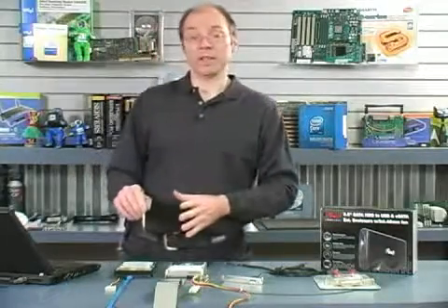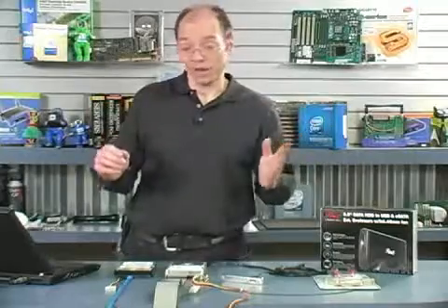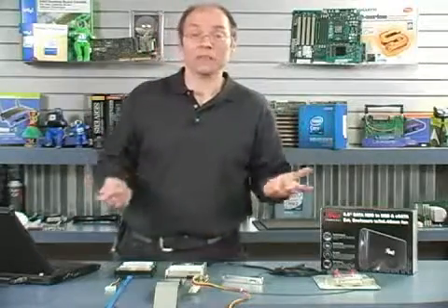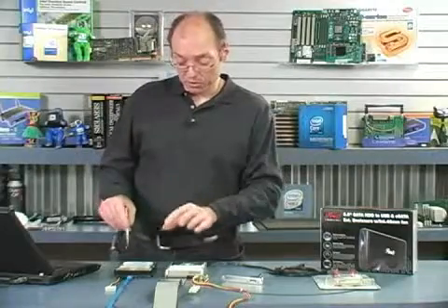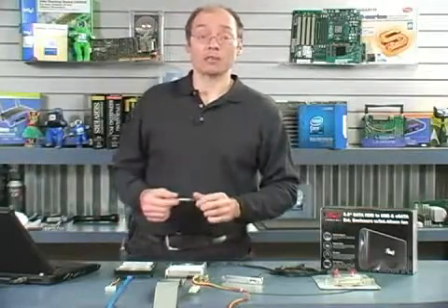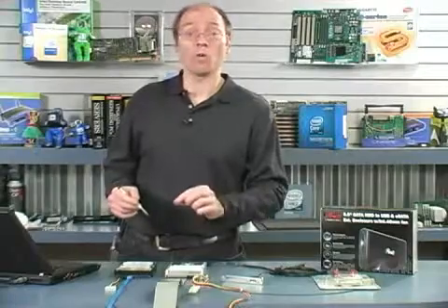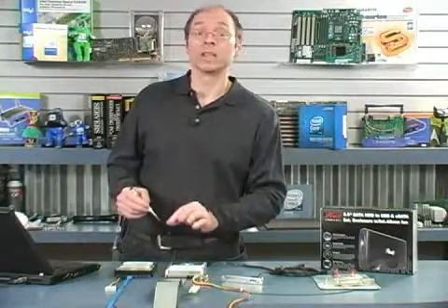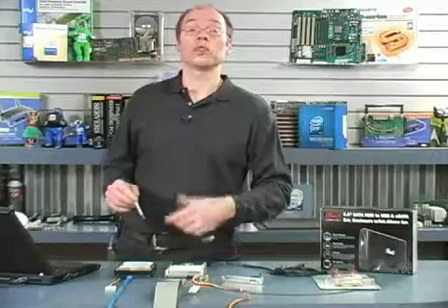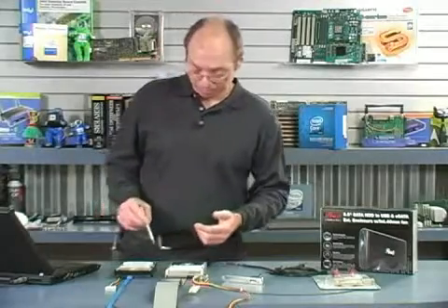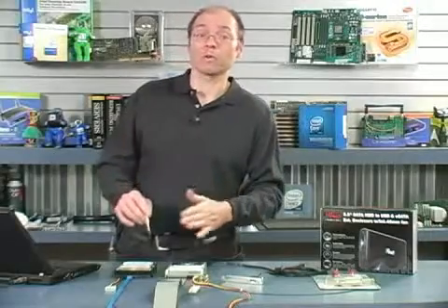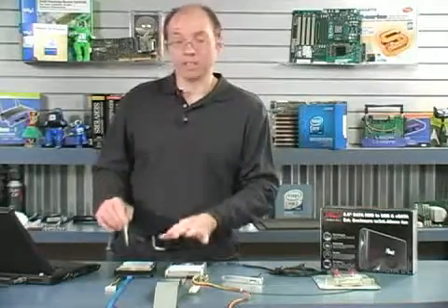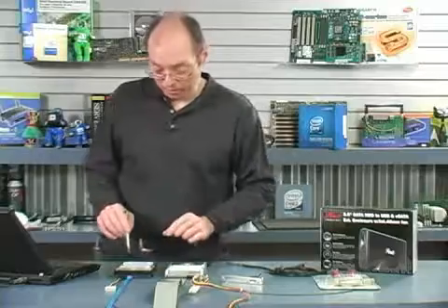Now, serial ATA drives, they don't have any jumpers, right? It's just a one connection. There's no master or slave. Well, that's not exactly true. You see, there are two variations of serial ATA drives available. Those that did the original 1.5 gigabit per second speed, and those that do the newer 3 gigabit per second speed. Sometimes those are called SATA 2 drives, which is actually inappropriate terminology. They are technically SATA 3 gigabit per second drives.